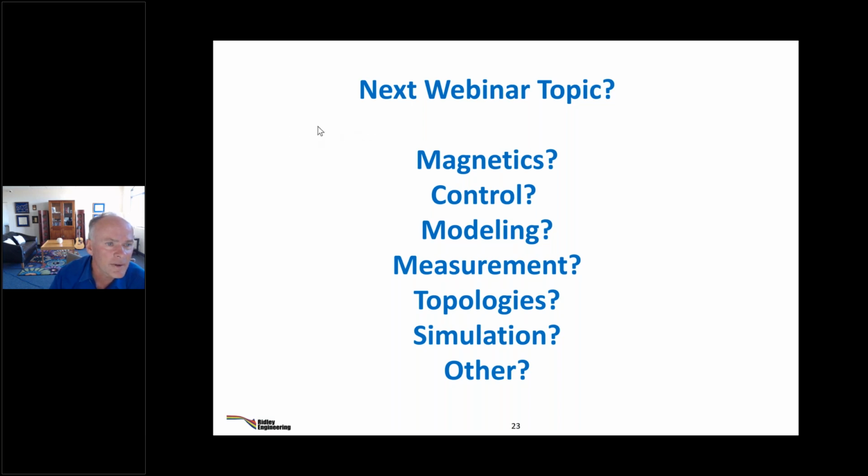How do we calculate the efficiency? Just look at each component. LT Spice is where I like to do that, quite honestly, because it does proximity loss like nothing else. It does all the harmonics at the same time on proximity loss. Nobody does that in any closed form way. They've tried, but they're not going to get there for an LLC converter. So efficiency, you just dig into that LT Spice model to get that.